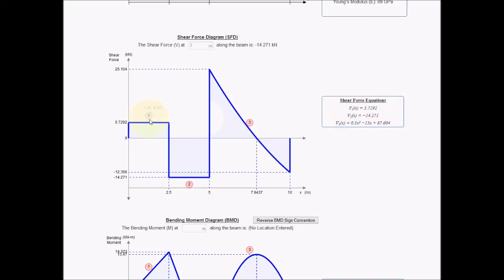They're just for your reference as well, so you can see what's going on within those beams, between the supports. So if we look at 6 meters now, there's 15.6 kilonewtons, and we can see that at 6 meters it would be referring to the V3 formula, so V3(x) there.